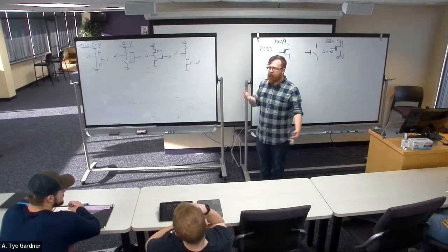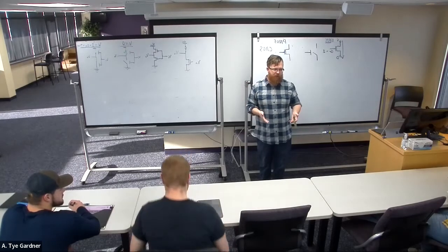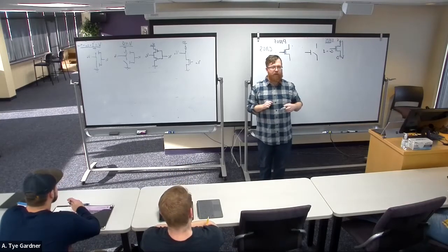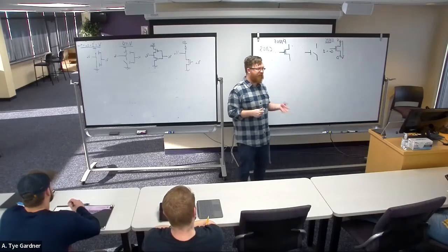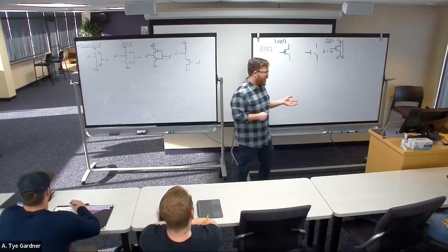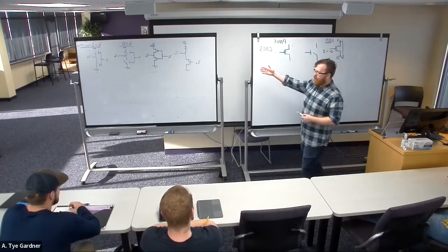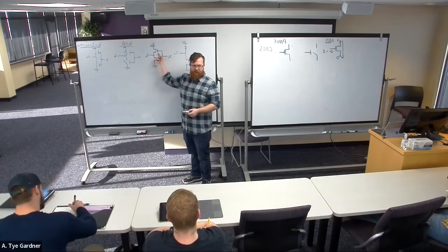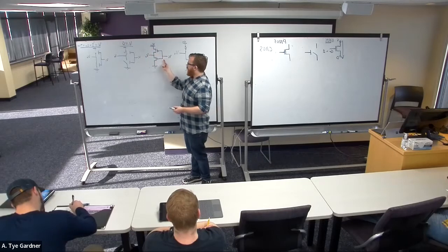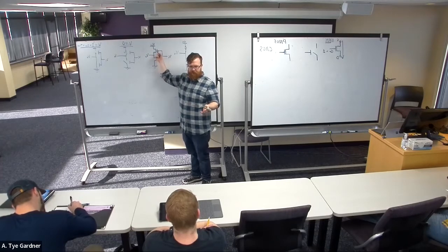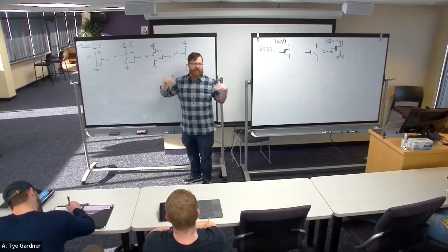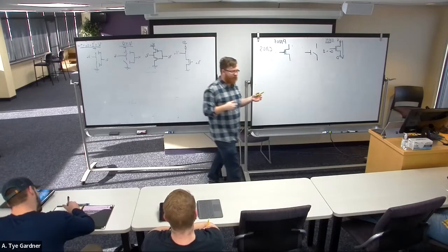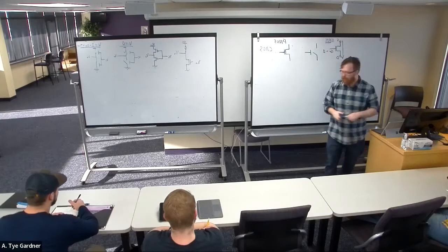Okay, so we're going to use this idea of a PMOS device and an NMOS device together, building a pull-up and pull-down network to make NAND and NOR gates. We're going to start with NAND and NOR gates because it turns out they're easier to design than ANDs and ORs. And we're going to see why: it's the inverting nature of the pull-up network. The PMOSs have to pull up. They can never pull down, which means if I put a 1, it sees a 0, it's not closed, and it can never pull up on a 1. It's just a logical consequence of the position of the PMOS device.